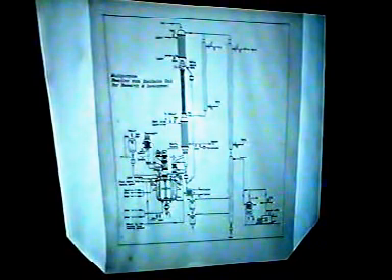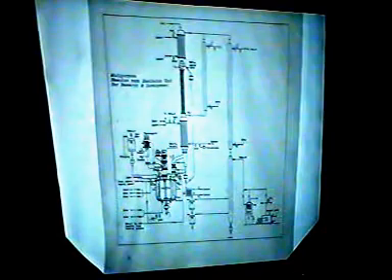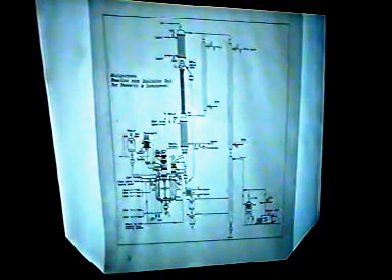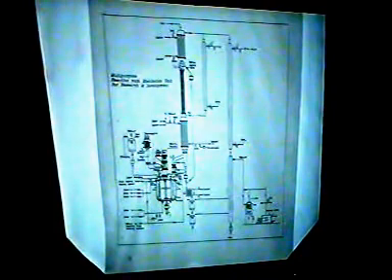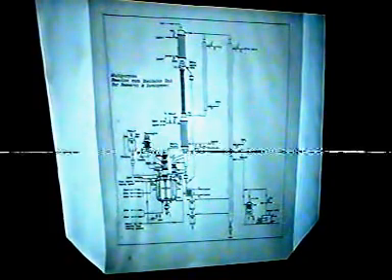The top dish is provided with a light and a side glass to facilitate viewing of the reaction in the vessel. We also have a side light and glass here which will facilitate viewing of what is happening inside the vessel. An arrangement to quickly detach or attach the vessel to the top flange is provided to facilitate the replacement of turbine or anchor as and when desired.